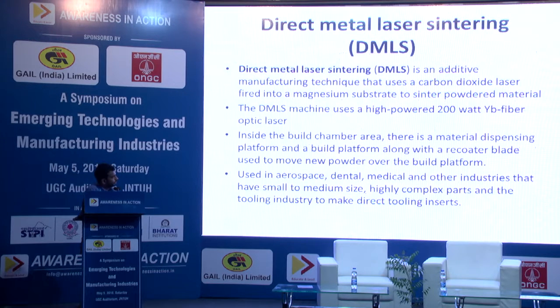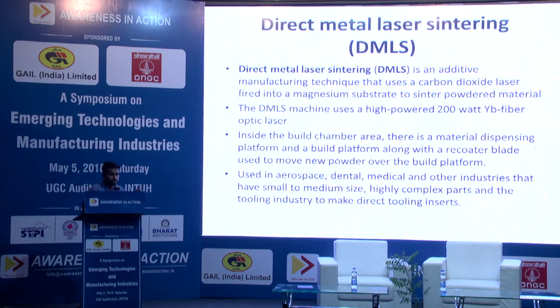So what happens in DMLS is again the same thing that you saw in SLS, but there are certain things that have to be maintained in DMLS, because here we are not talking about a 100 watt or a 60 watt laser. Here it will be a 200 watt laser, which is very high power, and the chamber is maintained with argon gas.